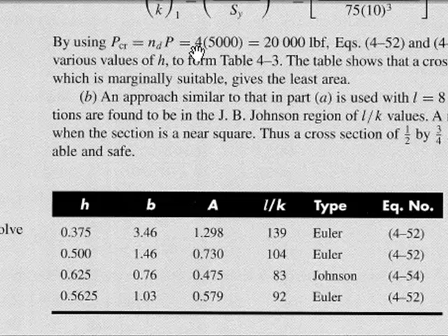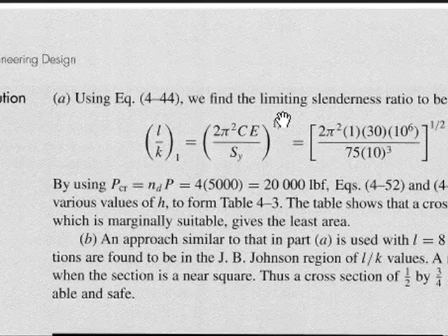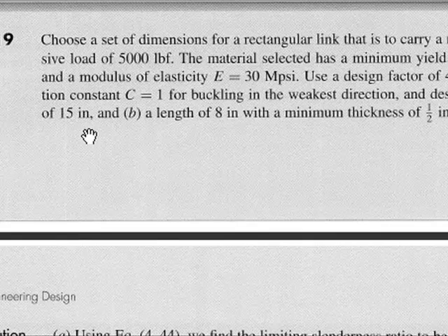It may only be about 3.95, but I think that's a reasonable exchange. We'll go with a slightly smaller standard size, and we'll only have a factor of safety of 3.95 instead of 4, but I think that's probably fine. This is the work that was done using a 15-inch length, as the problem statement said.